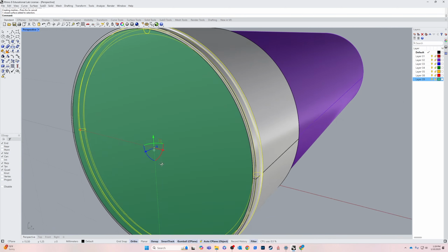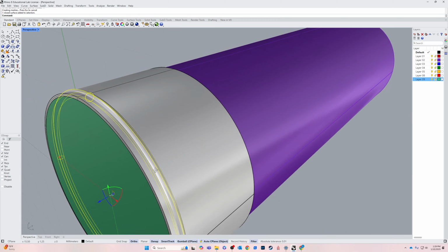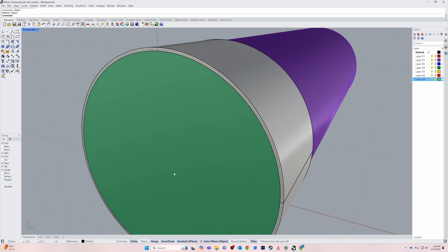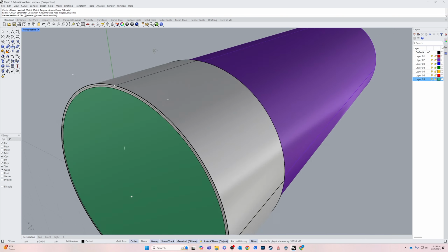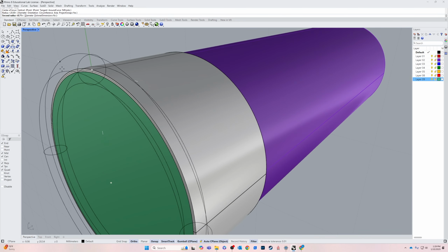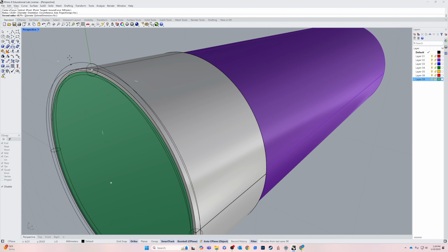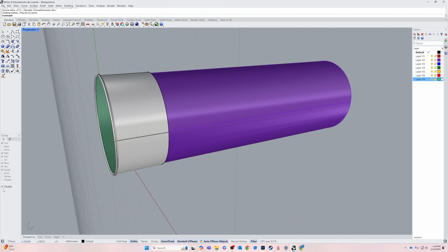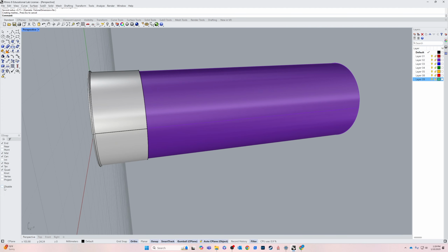And I actually need to, yeah, let me do that again. So erase the torus there, do a new torus, and go to the center. Then I'm going to click out here, and I just want it to be a little bit bigger. So you've got to watch your snaps. Sometimes you disable the snaps. It makes it a little easier to control because it won't try to jump onto a snap. Then get close. Click. Yeah, that looks good. Okay. Re-enable, so just undo the disable here. And then I'm going to pull this over about to there.